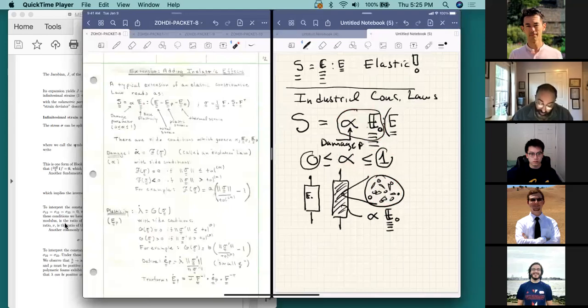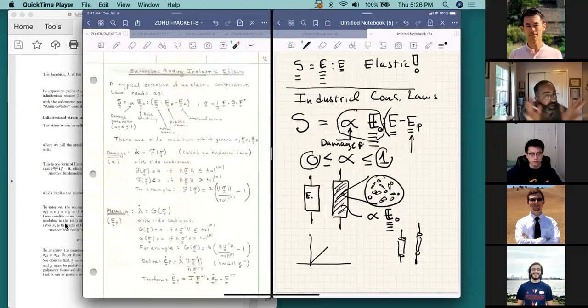Now, at the same time, there are other effects that we might want to take into account. For example, one in particular is the so-called plastic strain of the material, which is also an effect that is phenomenological. Basically, whenever we pull on a piece of material, and we keep pulling on it, if it happens to admit some type of plasticity, meaning some type of permanent deformation that stays with the material after I take my hands off of the stresses, we account for that usually with a model that looks like this.